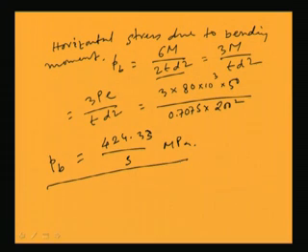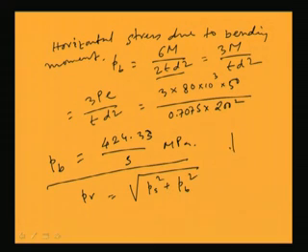Now, what we will do? Now, we will find out the resultant stress. Resultant stress PR, this will be basically PS square plus PB square, because PS is always acting vertically downward and PB is acting horizontally. Okay. So, the resultant will be PB square plus PS square.